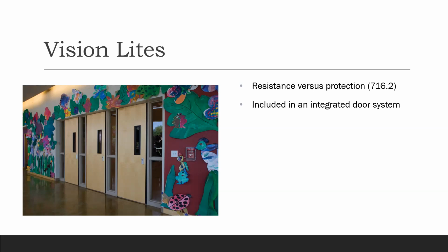Now I want to talk about ASME A17.1. ASME A17.1 is referring to additional doors in front of the elevator shaft, and it does have a provision about light kits. I want you to pretend that these doors on the screen are in front of an elevator shaft. ASME A17.1 says that there needs to be a vision kit in the first quarter opening for doors in front of elevator hoistways so that firefighters can visually see the elevator landing or lobby.